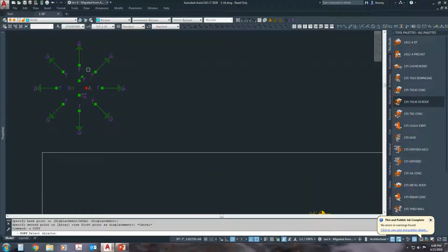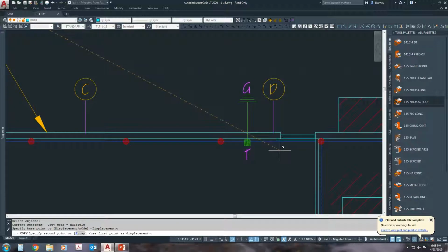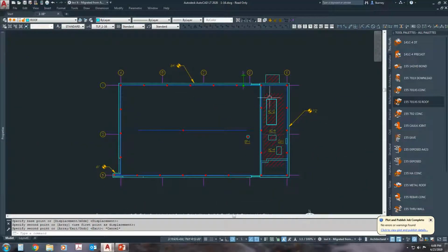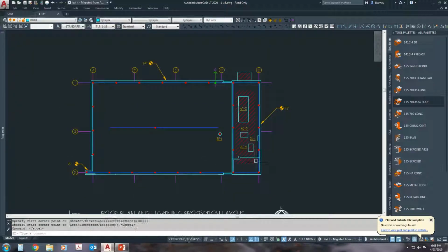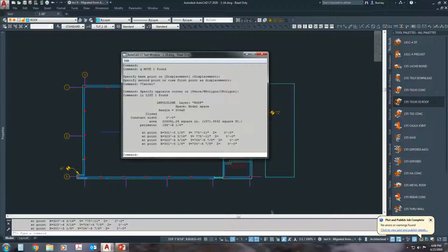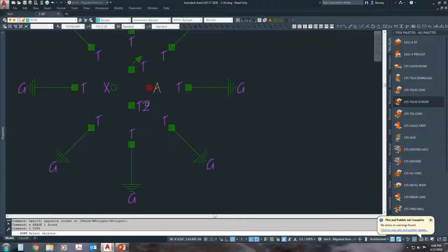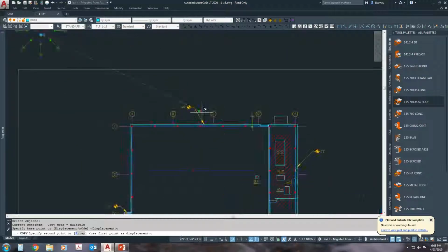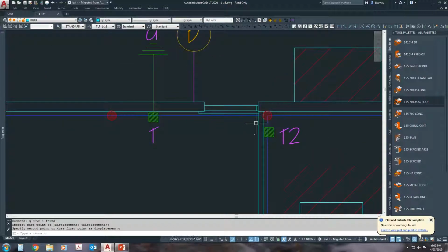We're going to use full down leads on this building since it is a concrete building. So what we're going to end up doing is, based on the building perimeter, which this one is 410 feet, we're going to end up having a down lead and ground every 100 feet on center. I measured that roof perimeter and decided it was less than 200 feet, which means we need 2 drops from the high roof to the low roof.